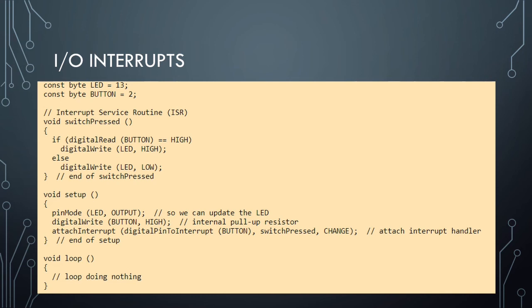You wouldn't want to wait 5 minutes to get through the loop to detect that overload. You would want to detect it immediately. So that's when you would put an interrupt at the beginning of your program to say, if this is happening, then we need to shut the program down, we need to shut the equipment down right away.